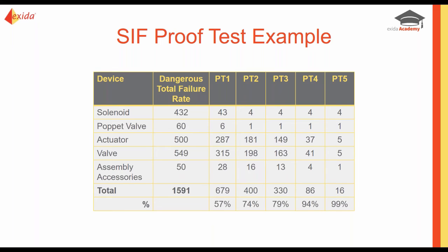That's awesome. So even with this, you do a full valve stroke test at operating conditions with a leak test, you still don't find everything. So even if you do everything you possibly can, you're still not perfect. So never assume 100%. But as you can see, you can alter your proof test coverage, your proof test effectiveness, in different ways. And of course, we know that not everybody can do everything.